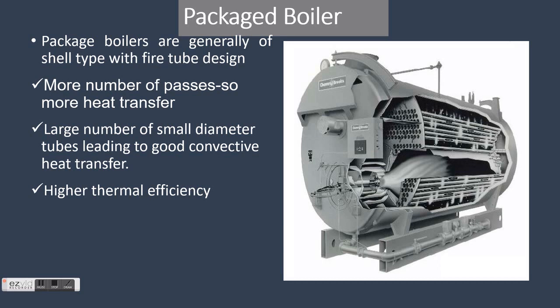Package boilers are generally of shell type with fire tube design so as to achieve high heat transfer rates by both radiation and convection. The features of package boilers are: small combustion space and high heat release rate resulting in faster evaporation. Large number of small diameter tubes leading to good convective heat transfer. Forced or induced draft systems resulting in good combustion efficiency. Number of passes resulting in better overall heat transfer. Higher thermal efficiency levels compared with other boilers.